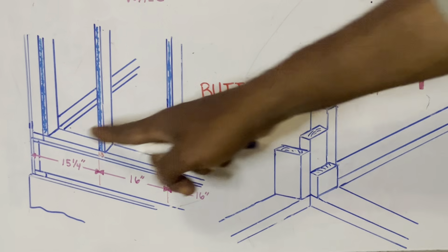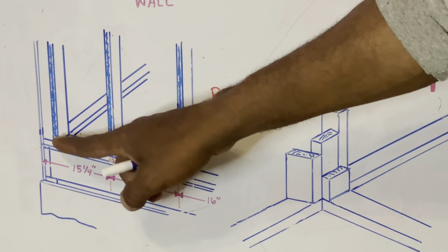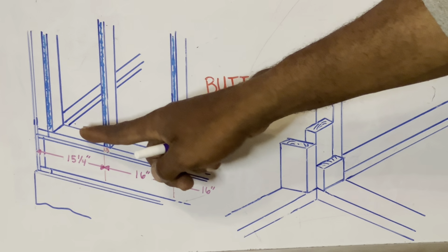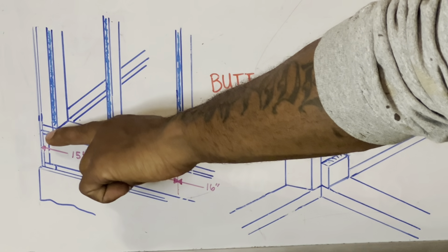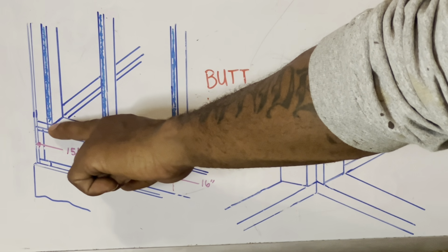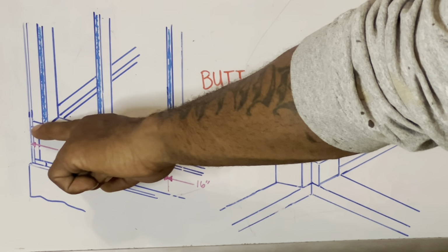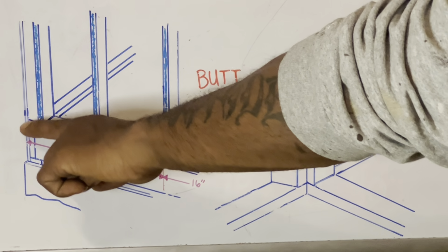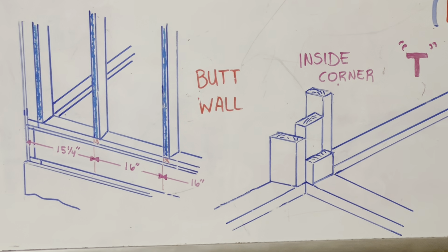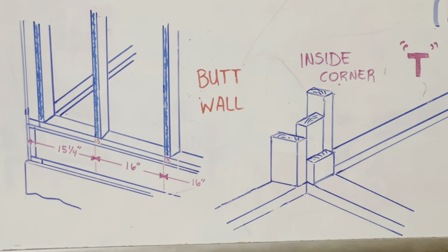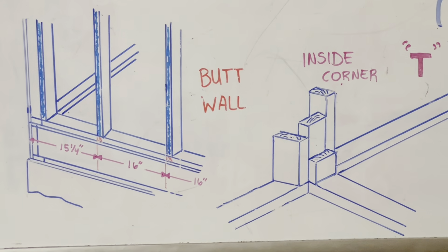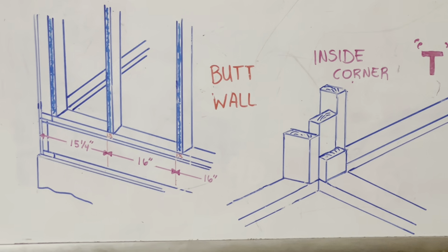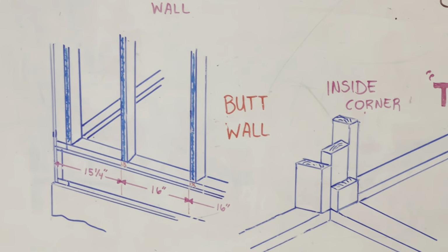That way, if you look right here, if I don't have these studs right here, and I've got my bottom plate just tacked in here, I can hook my hook right here on the outside of this through wall plate. I can either add that 3/4 of an inch sheathing, or I can nail a little scrap piece of the sheathing that I'm going to use right here, and then I can hook my tape measure on that and pull it out. But that's the point.